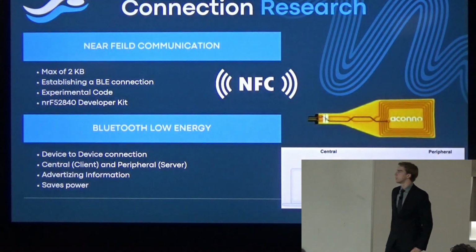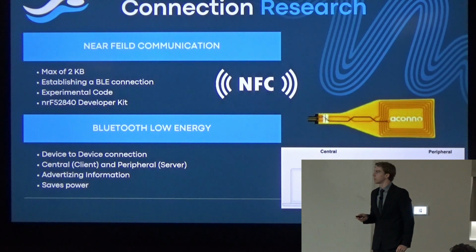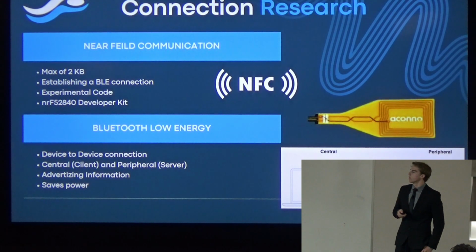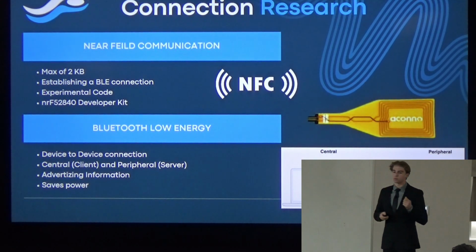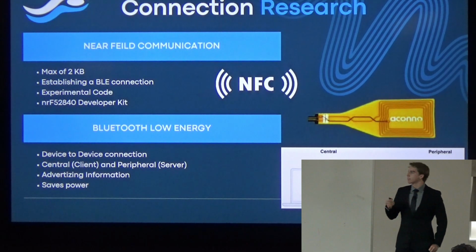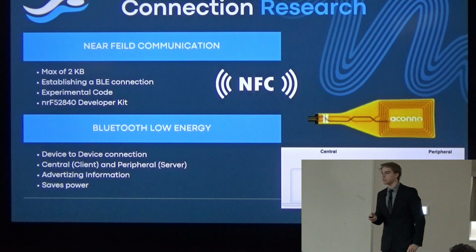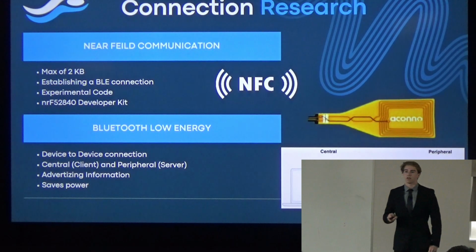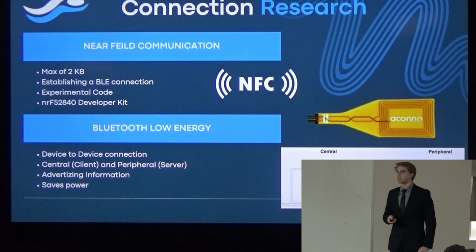So, connection research. This is where I had a couple of struggles, but I initially researched near-field communication, or NFC. This is the technology that is actually used when you tap your card or use Apple Pay. It essentially sends a max of 2 kilobytes of data, which was not sufficient for my entire thing, as a minute and a half of data was 616-ish kilobytes.